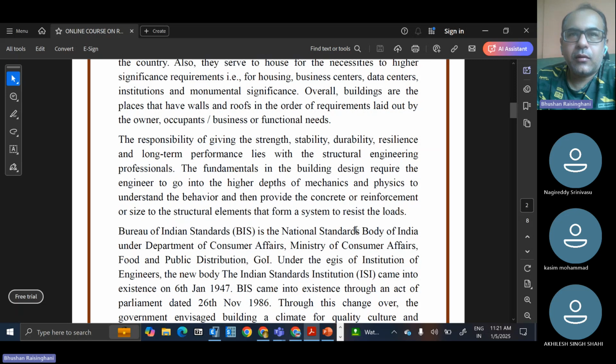Whereas when we see a beam or a column, it is bending and its deformation is not equal at all points. At the joints, joints are considered to be rigid. That's why the angle between beam and column is 90 degrees. That is what we assume. Once we consider the joint to be rigid, the angle between the two elements is not changing. However, the beam and column independently are bending with respect to their local axis.